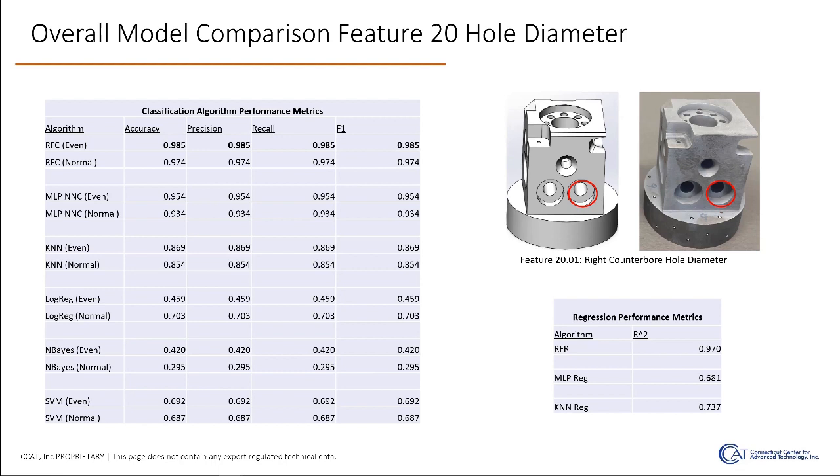And then instead of just classifying, we also tried a regression model, which instead of classifying the data into z-scores, basically a low, high, or medium residual, would try to estimate the residual value of each of the features. For example, if a diameter was supposed to be 10 centimeters, and the actual result was 10.1 centimeters, then the residual will be 0.1 centimeters.